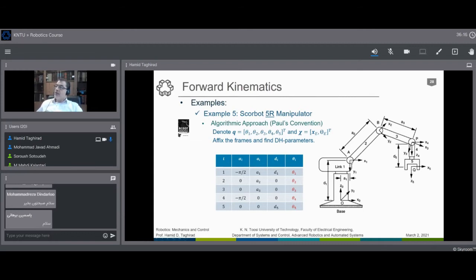And then again, the other ones are very simple, like the 2R manipulator. We have theta 2, A2, theta 3, A3, and here we have another angle which we can see, Z4 with respect to Z3, which is inward into the plane. Again, if we go from Z3 to Z4, it is along the minus X4 direction. So again, we have a minus 90 degrees here, and the parameters are finalized with the last end effector point that we have, D5. So we have 5 degrees of freedom here.